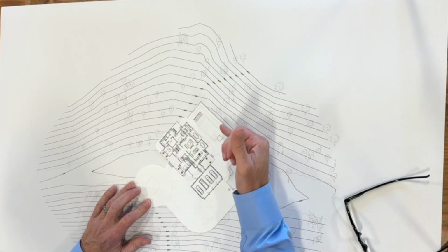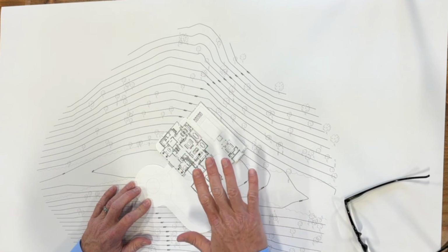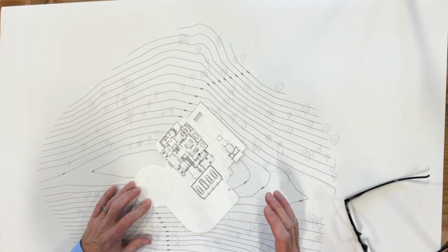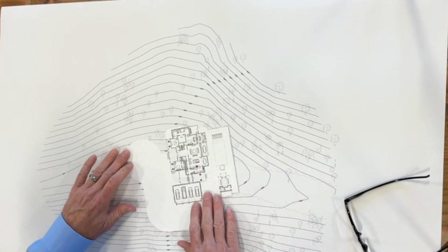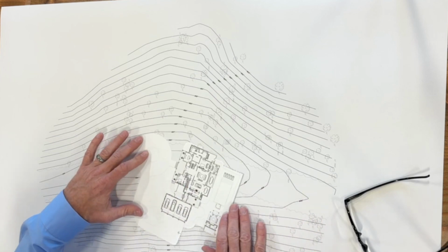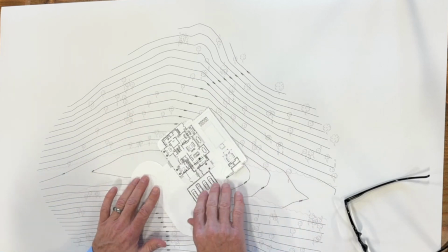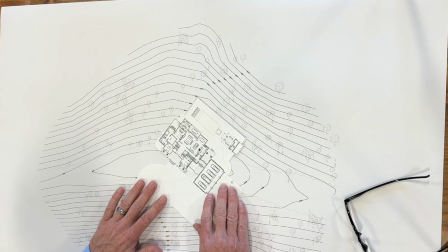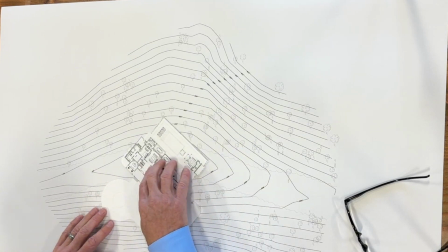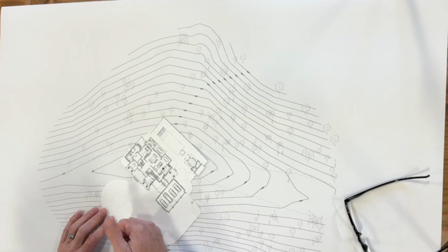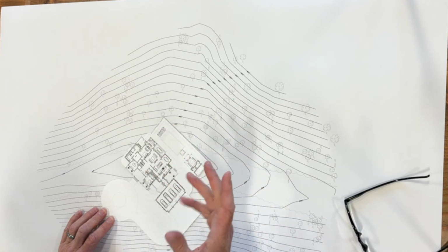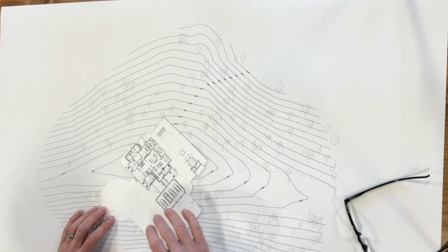And typically you're going to want the pool area to be at the same elevation as the home. So this really makes a challenge in that basically all of this needs to be at the same elevation, even though the ground is doing all kinds of different things all the way around it. And again, this could be tilted like this to look straight down the hill, could be going the other way, but essentially we're looking to have the back end go down to the river. Now you could argue that you could pull this over more and put the home right in the middle of the hilltop, but then the driveway, which also has to stay flat, would need massive retaining walls over here, even though you're minimizing a retaining wall here. So it's always a fine line between optimizing one of the two sides of the house.